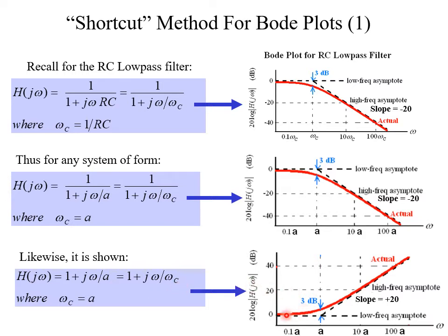The only difference is that instead of falling at 20 decibels per decade at the corner, once you get to the corner, it moves up at 20 decibels per decade. This is not a complete surprise because this is a reciprocal here and there's no reciprocal there. When you take a log, the only difference is a power of -1, and that power of -1 leads to a minus sign in the slope. So instead of the slope being -20, the slope is +20.